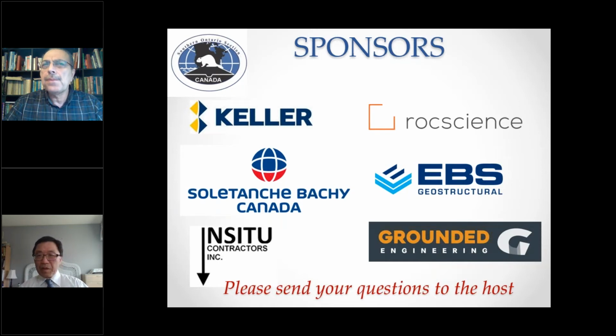Okay, thank you. And also, according to one of the slides you presented, the comment about the shorter reference beam for the parallel test, and according to the photo, it can be observed the distance of the reference beam to the edge of the test pile may also not be sufficient. So I think this may also be one of the issues creating an untrustable, unacceptable result of the pile test.